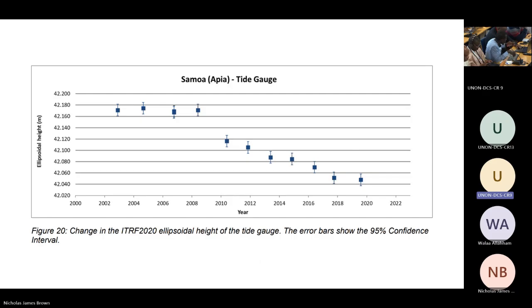I think that could be an alternative. Of course, we'll be in phase with the national referencing, therefore the importance of modernizing our geodetic referencing systems, because if we have ancient systems and you have PPP-RTK, then we have to have different adjustments to ensure that our positions on the high seas are defined according to the national referencing system. But here we don't have this obligation. I think with PPP-RTK, we can have greater levels of accuracy. Thank you.